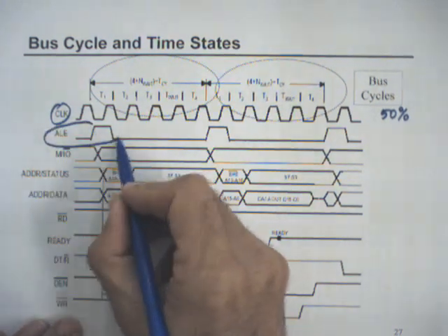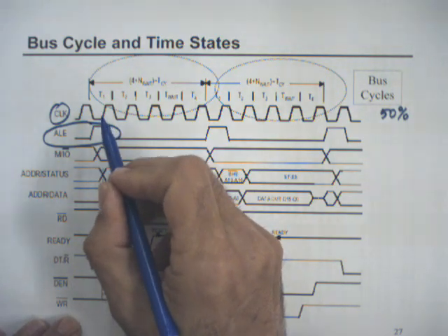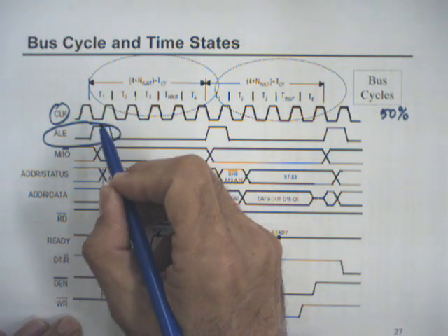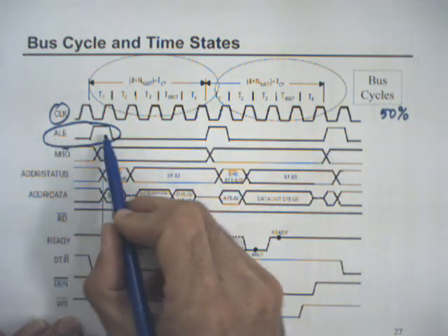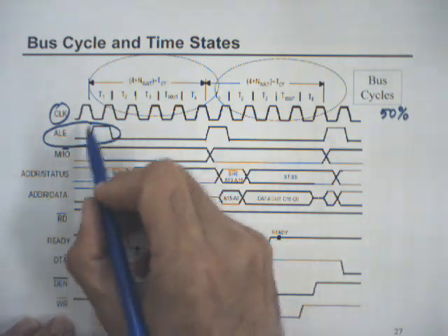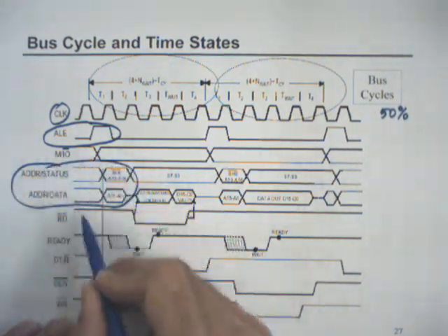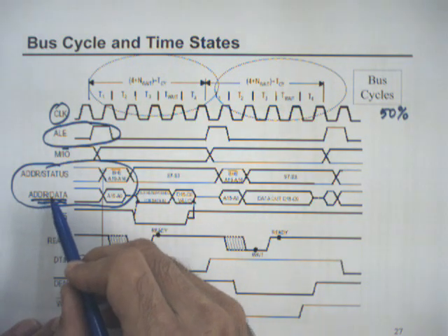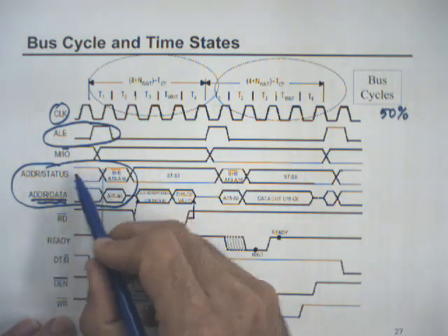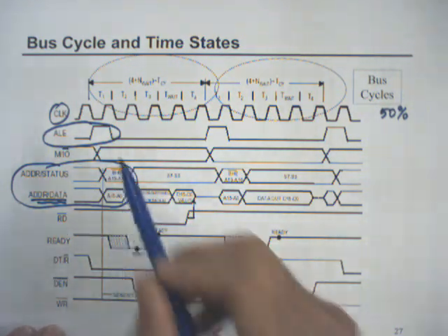Okay, address latch enable starts to store the address information to the corresponding latches. There are 3 latches, you remember, in 8088 and 8086 processors. These enable these latches for address type of activity, address control and address data. This is for multiplexed pins. Each pin may be address or data depending on the condition. So it's controlled by other control pins like this. So the others are later.